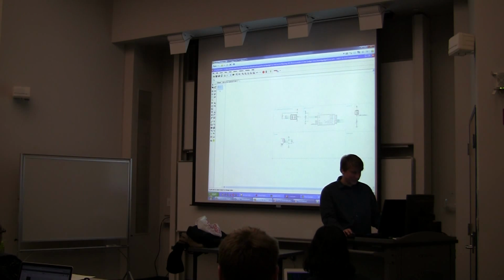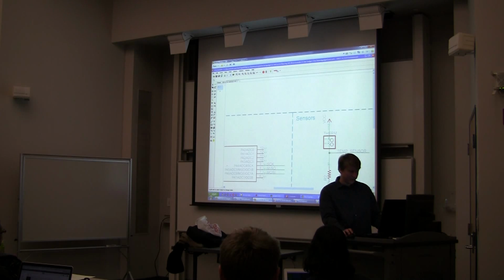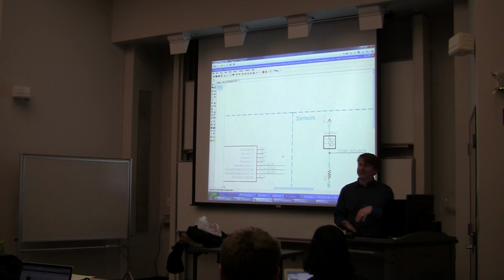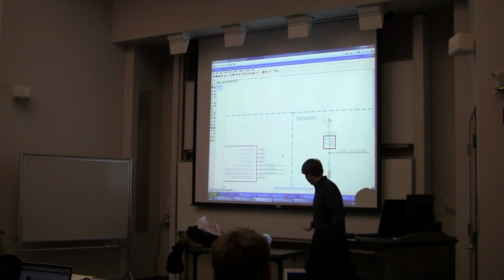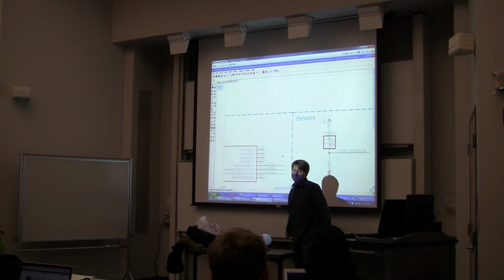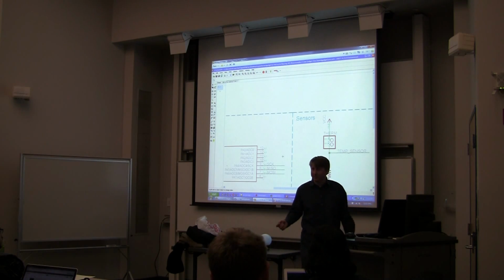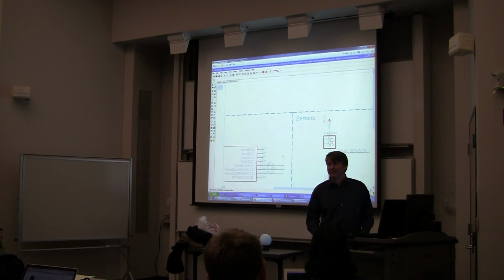So the way we have this, we just have this little connector. We could be on the board or off the board, right? Because I could either solder the thermistor directly in, or I could put a little header there, kind of like what you guys plug in your USB port, and then I could run wires to a thermistor somewhere else. You know, because maybe, let's say that all the heat generated by the wall board was right next to my thermistor. That would give me a very accurate picture of what the room temperature was. So I might want to move the thermistor far away.